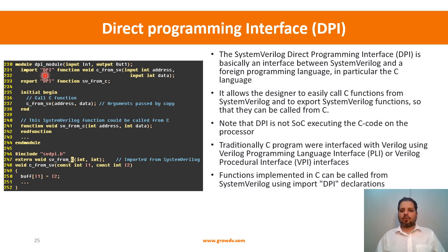We are not going to go very detailed into it. It's a specialized area. Basically, the main thing with respect to DPIs is how you convert various SystemVerilog data types to C data types, and from C data types to SystemVerilog. That is the main core problem that you will face when you explore DPIs further.